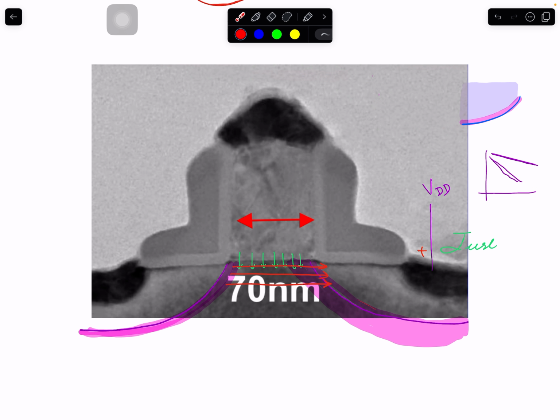And because threshold voltage lowers now, because we can turn on the transistor pretty easily, pretty quickly, a whole new phenomenon happens, which I'll talk about in a minute. This is the short channel effect. It impacts everything: current, speed, threshold voltage, and therefore the off current and on current.